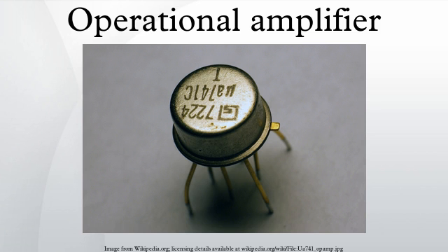Op-amp characteristics, ideal op-amps. An ideal op-amp is usually considered to have the following properties: infinite open-loop gain G equals Vout/Vin, infinite input impedance Rin, and so zero input current, zero input offset voltage, infinite voltage range available at the output, infinite bandwidth with zero phase shift and infinite slew rate, zero output impedance Rout, zero noise, infinite common mode rejection ratio, infinite power supply rejection ratio.